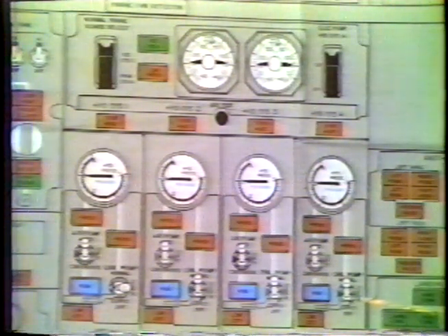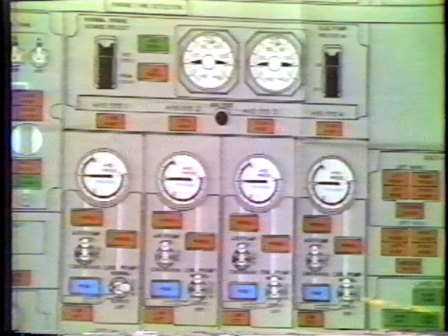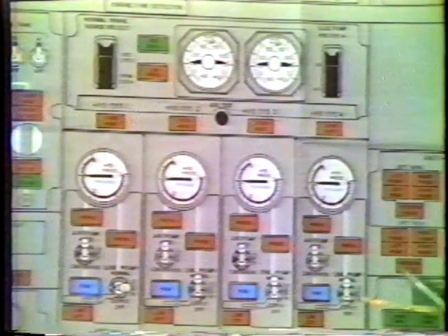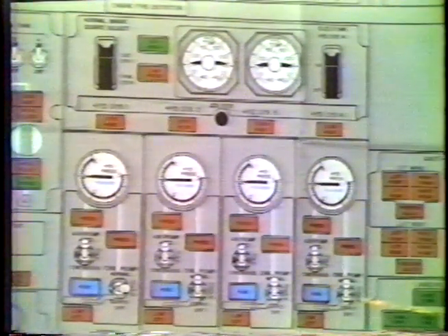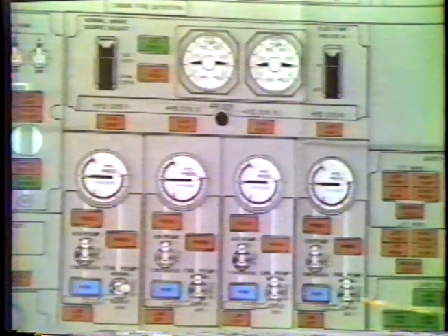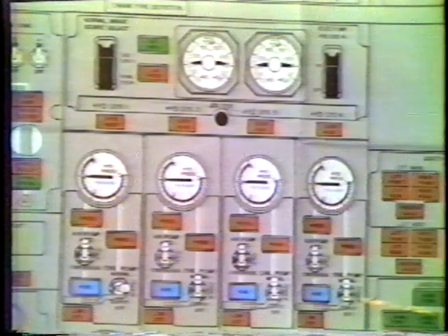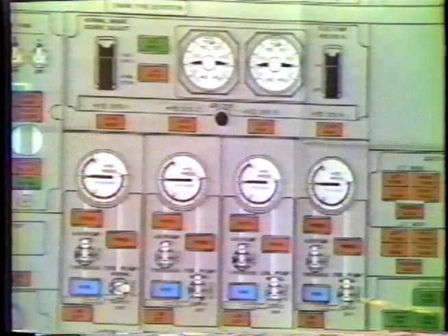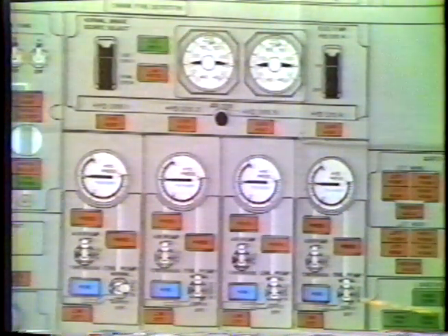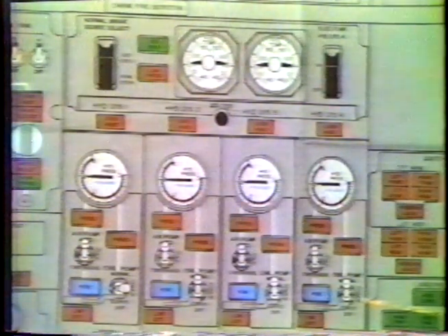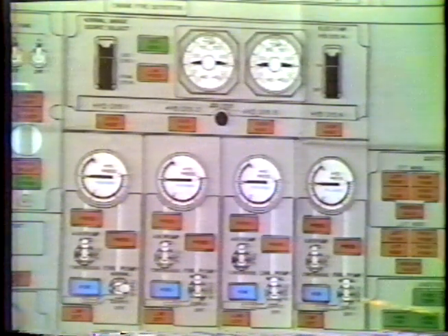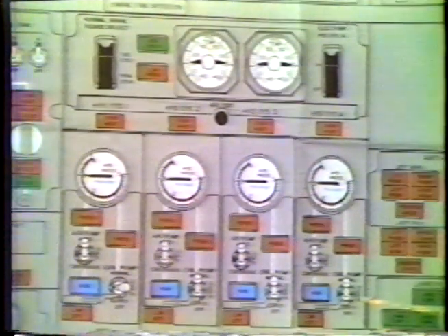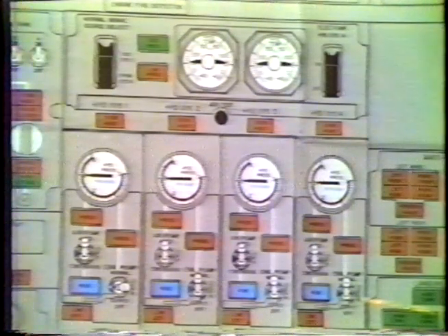Flight controls. All flight controls are operated off of all 4 hydraulic systems. Exactly what flight control is operated by what system can be referred to on the overhead panel, and there's a schematic diagram there which we'll discuss when we get to that particular panel. But they're all right there in the cockpit. It'll tell you exactly what operates each system. Stabilizer trim and autopilot are on systems 2 and 3.